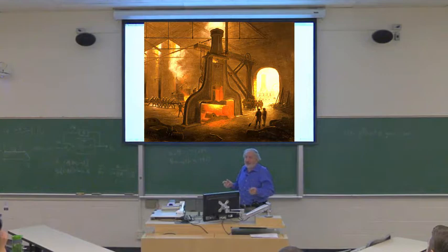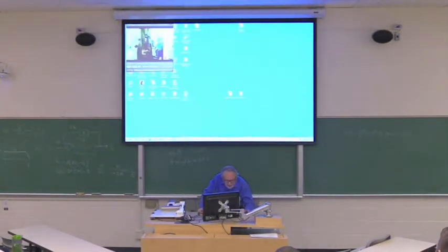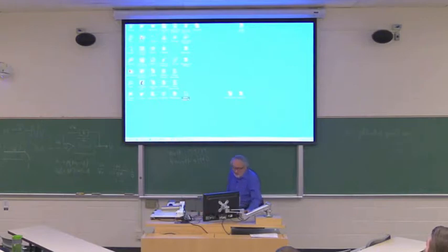You may not be aware of it, but all big machinery is still done like this today. If you look at the shaft of a wind turbine, or big gears, anything big today is still done exactly like this, and the machine looks exactly like this. So the trick is how to control it if you want to forge, like, an octagon or square, and you have to forge it very accurately. So the trick was some kind of a servo, and I'll show you now a quick video to show you the servo.